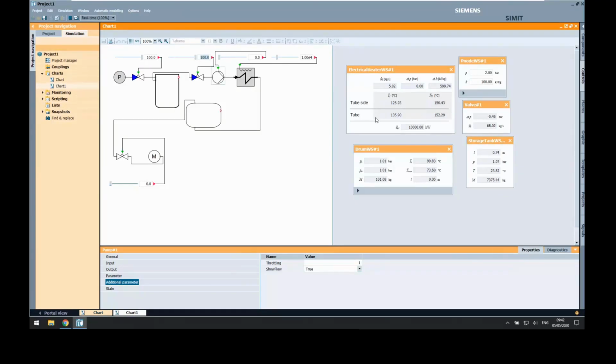But because I have 10 tubes, the last tube is still gaining temperature. So this is slowly filling with water now. And if I wanted to start filling with water faster, I could maybe use my pump. So we are currently pumping 8 grams per second. This is slowly going down while the temperature, the pressure in the chamber here increases.